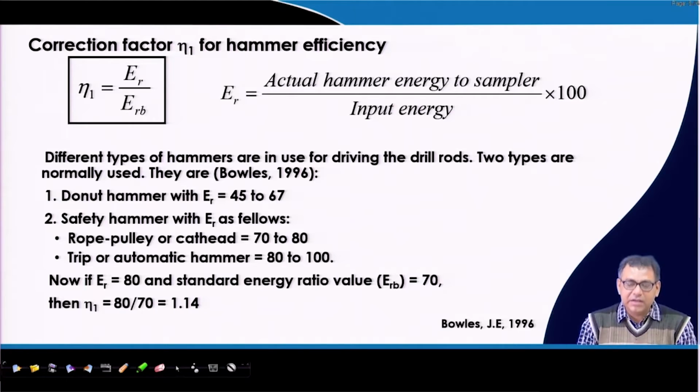So, there is a standard energy that we are applying during the blows. Okay? So, we know that this is my height, this is the weight, and this will be the free fall. That means everything is standard. Based on that we will get the input energy you will apply during your test.